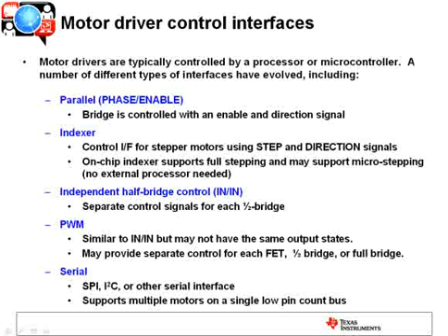These provide independent half-bridge control. They're somewhat of a legacy interface. You'll see PWM interfaces referenced. Now those can be very similar to the N1, N2, or they can be different. It just depends upon the H-bridge logic output states.